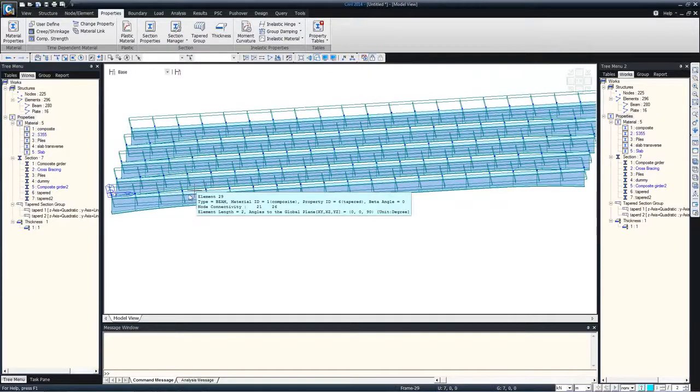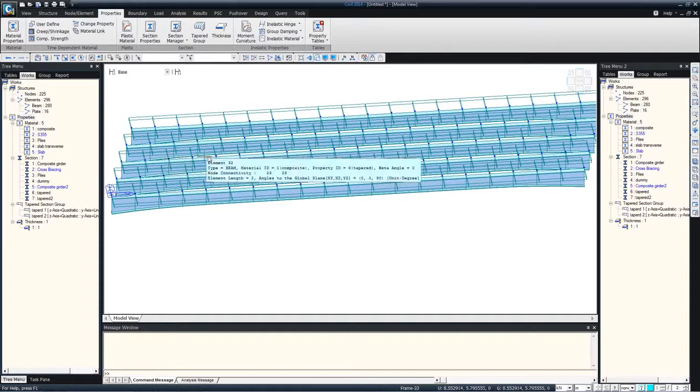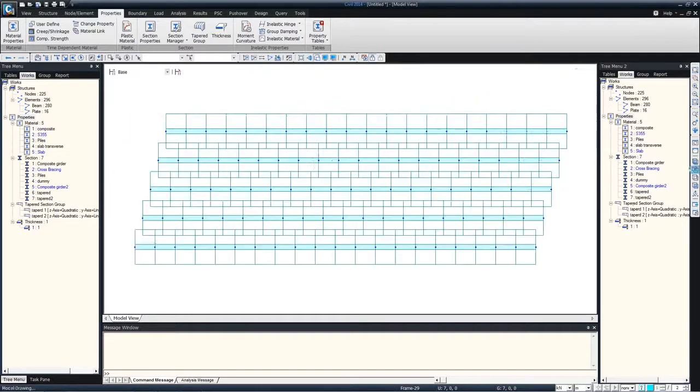Now Eurocode also says that the 15% span on either side of the supports should be considered as cracked, so the fully cracked deck. So we need to do that. I'm assuming that the first 4 elements here on each girder should be cracked, but you should always have a node representing the 15% span so that you can identify which sections you want to crack.